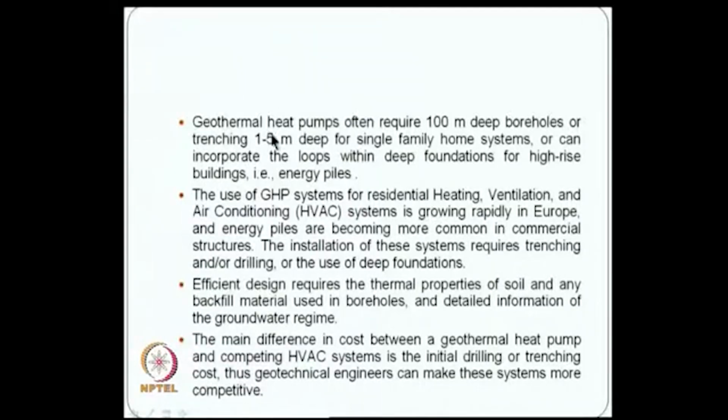The geothermal heat pumps often require more than 100-meter deep boreholes, or trenching 1 to 5 meters deep for single family home systems, or can incorporate the loops within the deep foundations for high rise buildings and energy piles. So, the concept of these energy piles is what is being followed in UK and other places. I in fact highlighted this in one of the earlier lectures in the beginning, when I discussed the scope for ground improvement.